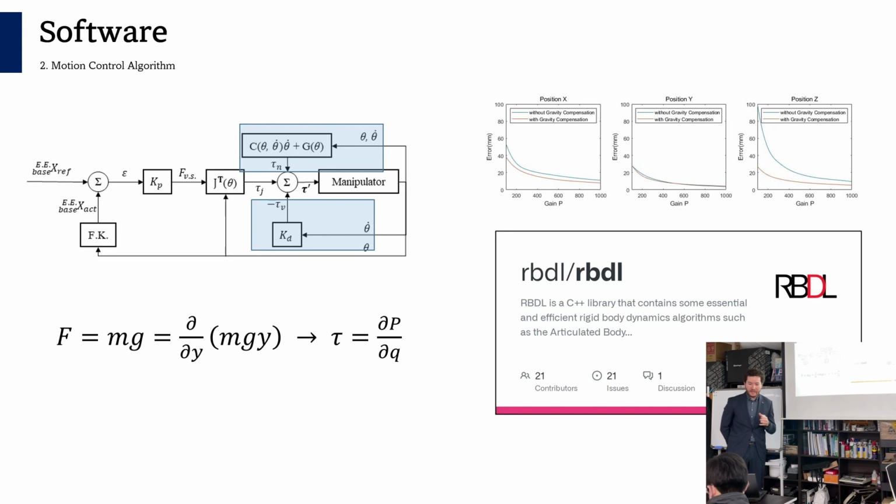Joint space viscous damping torque is simply a joint velocity vector multiplied with a KD gain vector. One important advantage of utilizing joint space damping instead of task space damping is that it enables individually tuning gain values for each joint. This is especially important for generating smooth motions for my manipulator, which has different types of actuators for each shoulder and wrist joint.